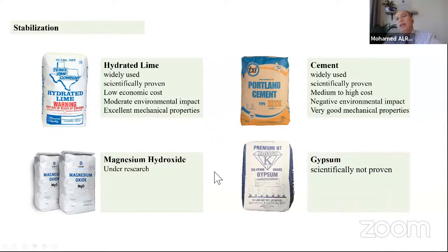The fourth stabilizer is gypsum. Actually, I'm sorry to say that gypsum is not scientifically proven yet. We don't know exactly what type of chemical reactions happen when you add gypsum to soil that contains a clay component. This is why I say it is not scientifically proven yet. It was used, but it is not widely spread, by the way.